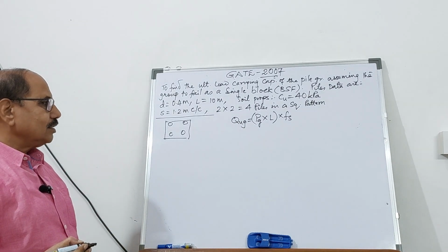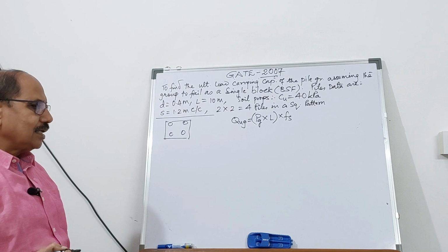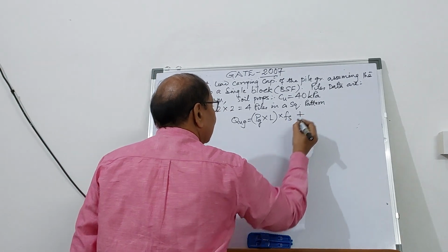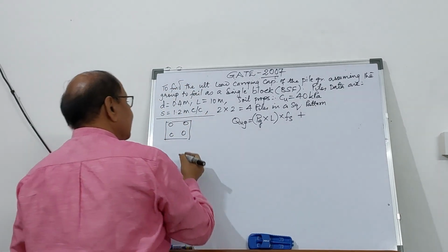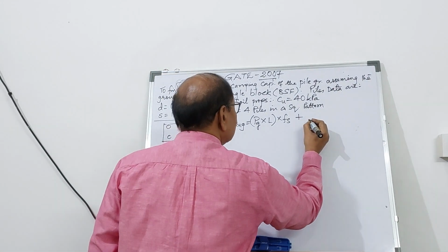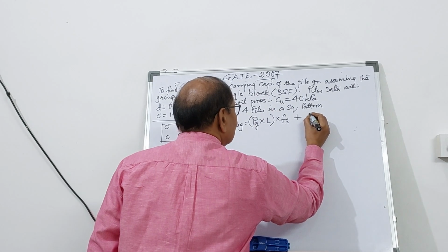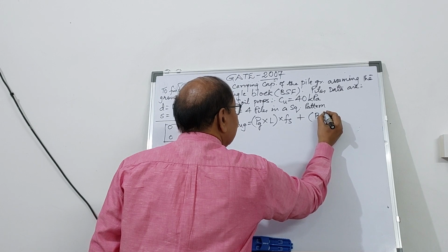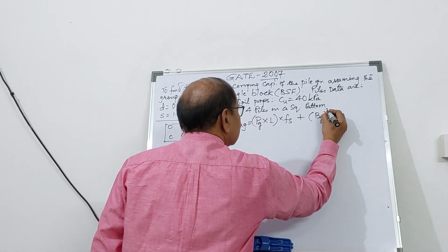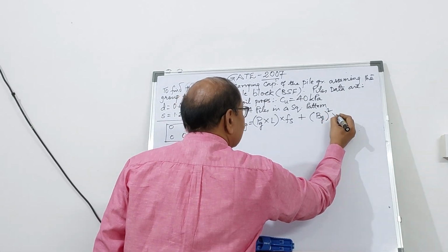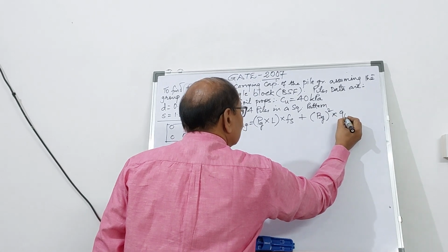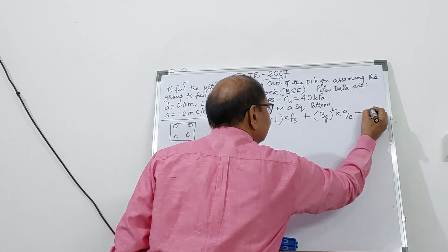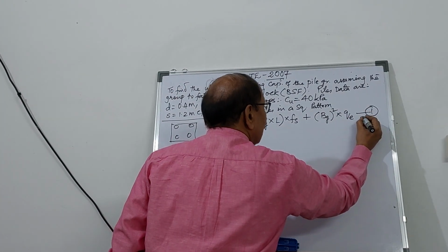So plus the end bearing resistance, which is going to act over the area of the group, which will be the width of the group in a square pattern, the whole square, multiplied by the unit end bearing resistance. So there is the formula based on block shear failure.